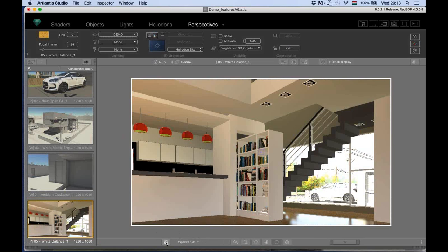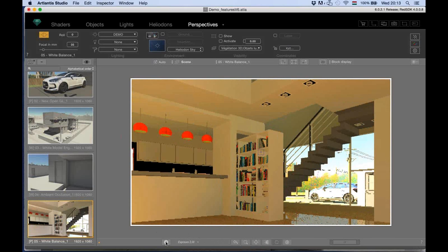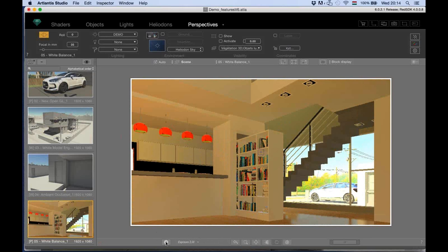If I switch back to exposure, you may note a color overlay, a kind of yellowish tone on the whole surface. This is because the exposure mode deals better with the colors. It takes into account the color temperature of the light source as well, which refers to the relative warmth or coolness of the white light. In addition, we have here a scene with a yellowish parquet that produces a color bleeding as well. And this is a phenomenon we may note from reality.